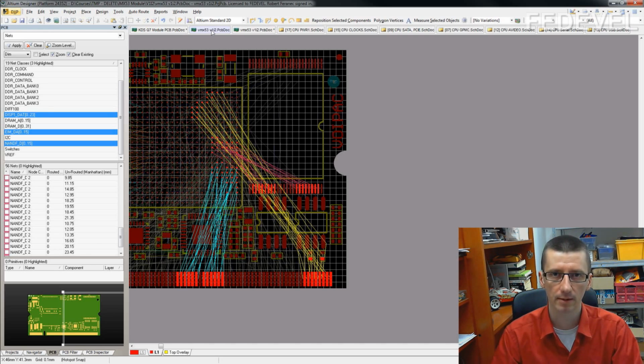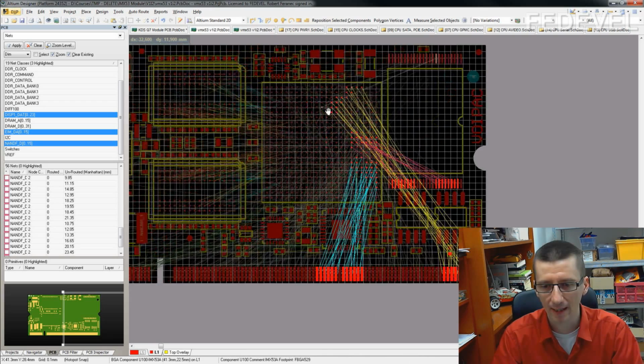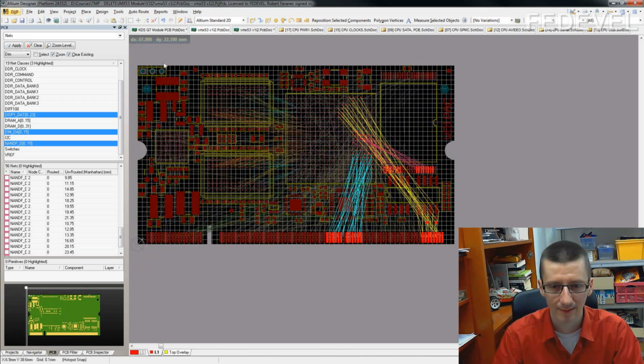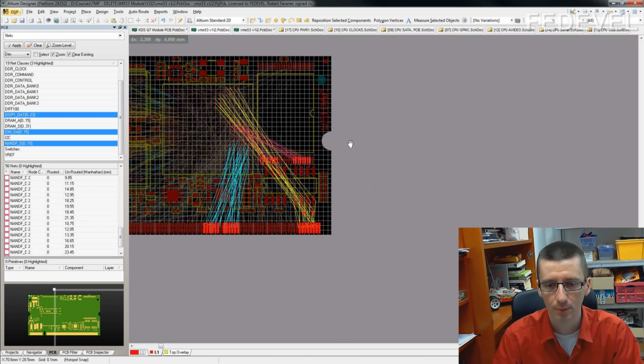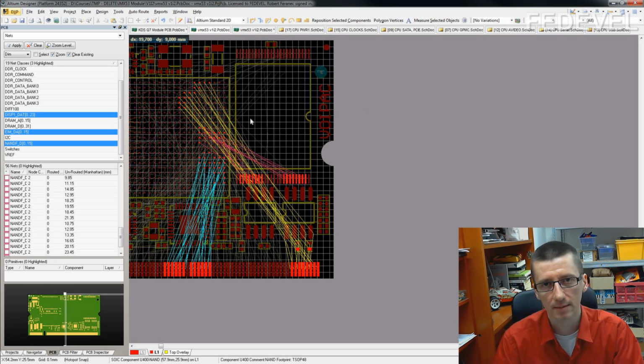How exactly the track looks right now is not important. Important is you do all the buses in a similar way. You don't connect this pin like here and the same pin from the via this way. That's what I was speaking about. You don't want to do it this way. Do them in a similar way.